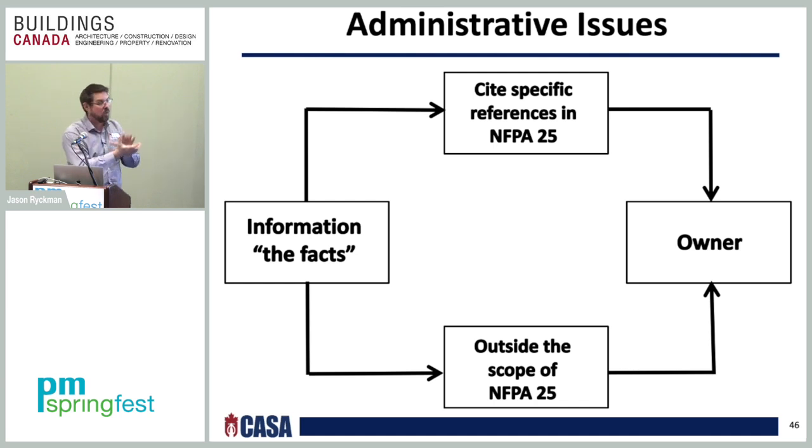And that owner or owner's representative has to keep those records. In NFPA 25, those records are 3 records: the record for acceptance, the previous record, and the current record, which need to be maintained, and the owner shall have them.